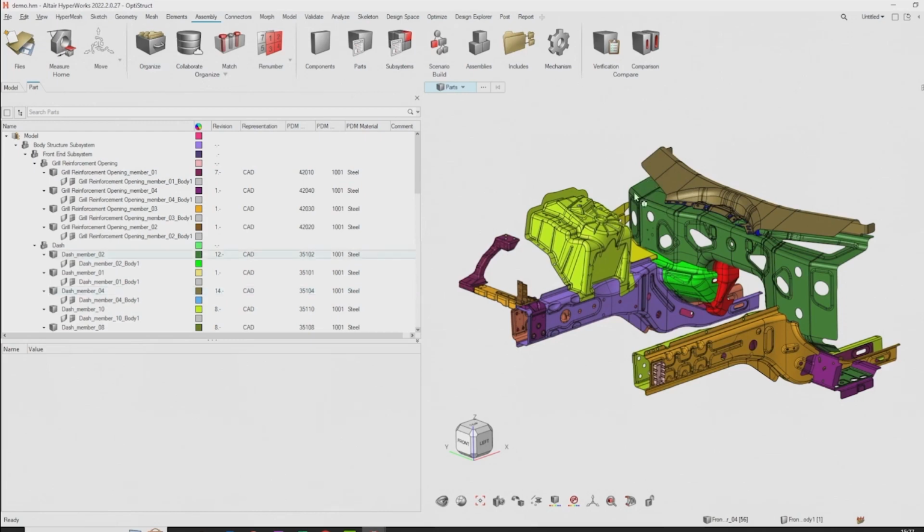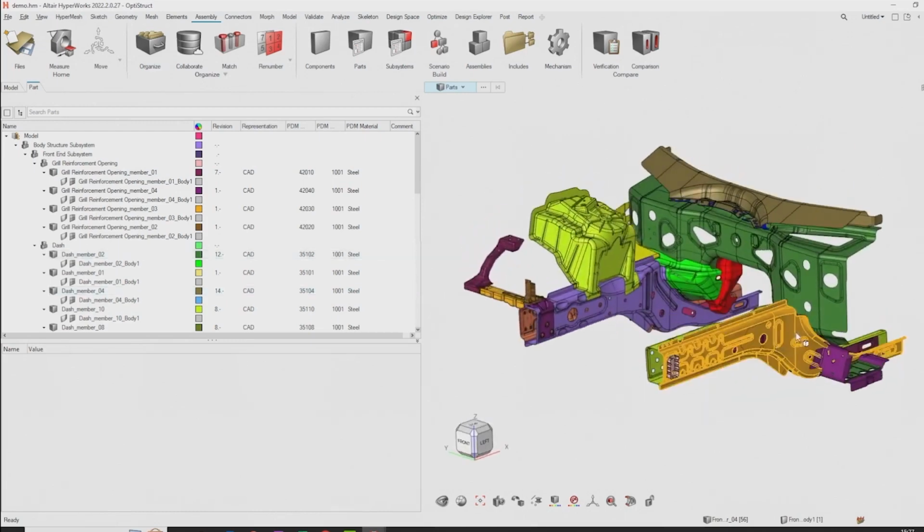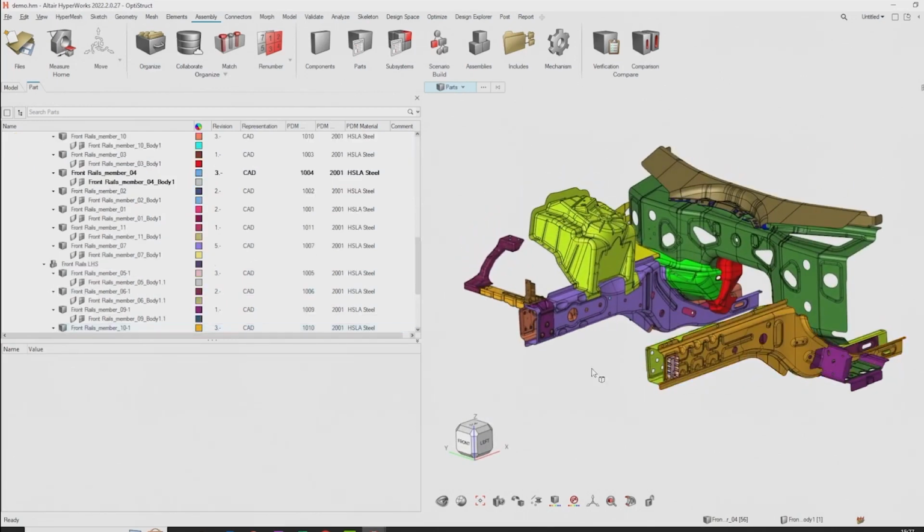So we take one of these sheet metal parts. It's a single thickness, so you may model that as a component with a property of a single thickness. So for us, that would be one part as well. So one part, one component. The same applies if you were to solid mesh something. If you solid mesh something, you'd have one component with one PSOLID property if you're in OptiStruct, a solid property card. And that's, again, one component, one property. For us, again, one part.